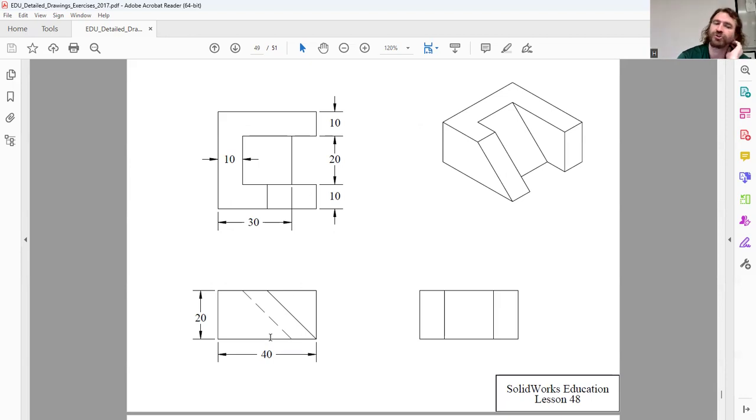The other option is drawing the profiles that are here in the front view and then using the extrude tool itself to offset where those extrusions are. And that's where I think it's going to be more interesting. It'll be more instructive of a part file to do it that way, but it is not the only way to do this part file. But this is the way that I'm going to do it.